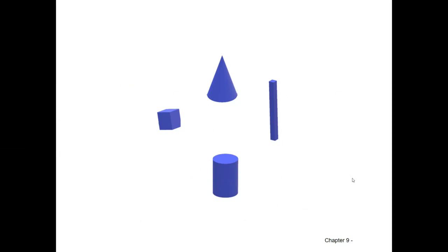Before moving to the next problem, let me just explain what is happening in this slide. Here we have 4 different geometric shapes. One of them, the one at the bottom, is considered as the riser, and you know what the riser is doing now. And we have 3 other geometric shapes. These are intended products to be produced in a mold. So we are going to design a mold which is able to produce all 3 parts on the top, making use of this riser. How do we arrange them? How do we put them in the same mold system? Do we put them on a random basis, or do we do it in a certain order? Of course, there is a certain order to be used for this purpose.